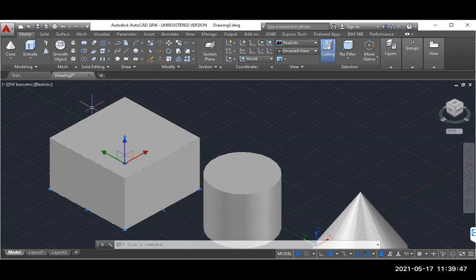Another way, how you can generate this box. This box we have taken from these ready-made primitives. Now if you want to draw that box, you can draw points. Using those points you can draw lines. Using those lines you can create surfaces, and through that surface you can create some volume. So now here you can see how we are moving to draw that box.